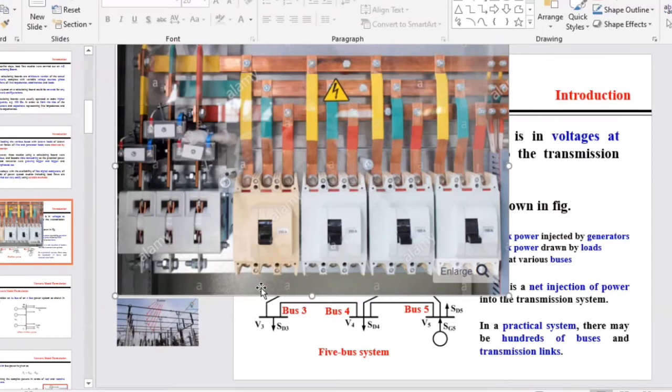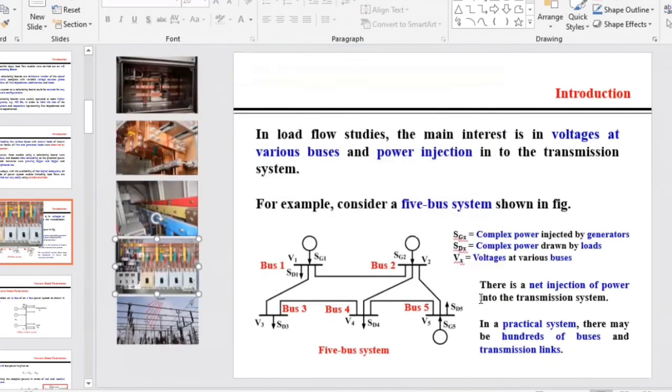When something goes wrong in our electrical and mechanical operation, we immediately shut it down. If you find that a pipe has burst where the water was flowing, you shut the incoming valve off. The same thing, if you find that something is wrong in the bus bar or in the outgoing, and the switch is not working, you switch off the incomer circuit breaker.